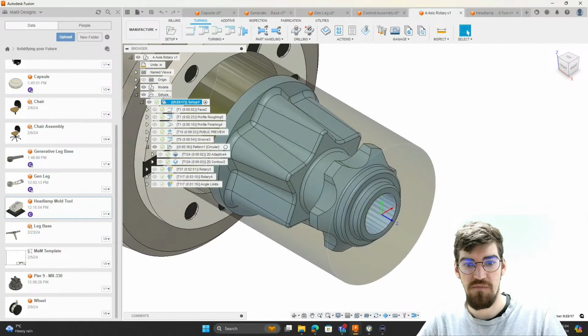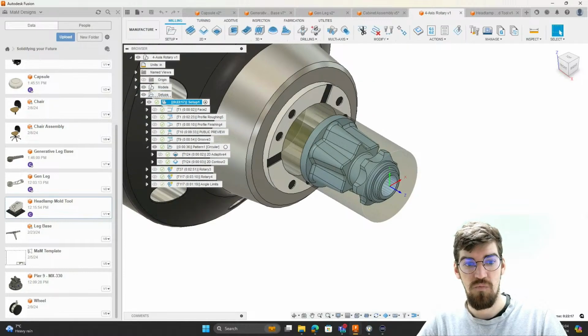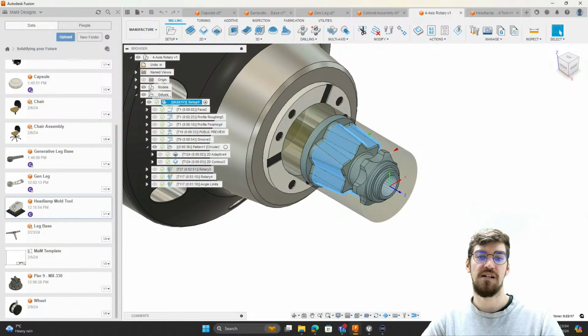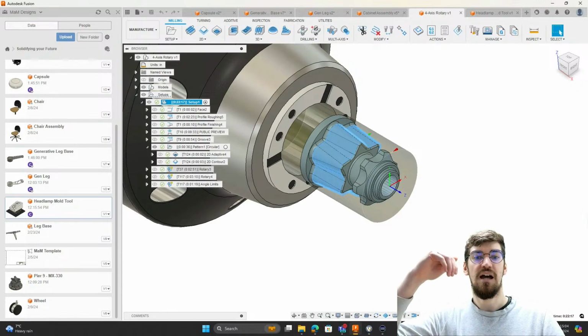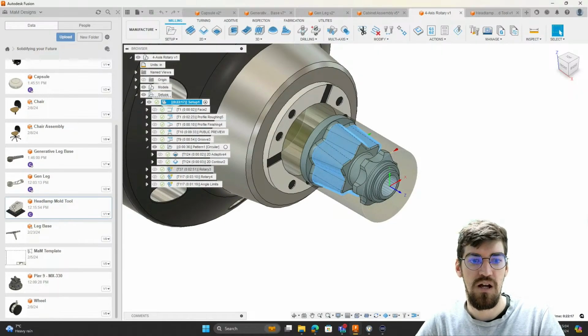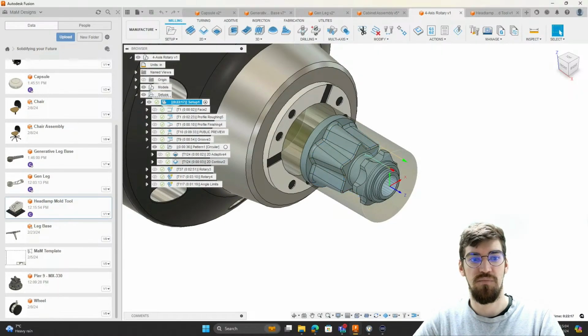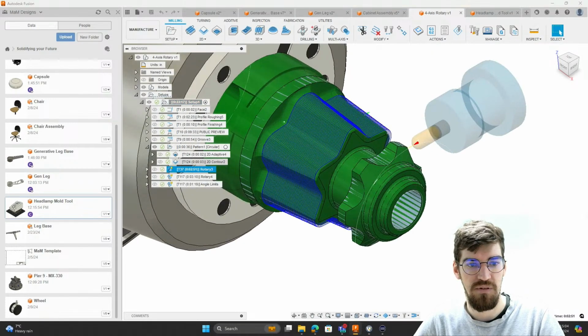Using some of the tool paths that we've got available to us within the extension, one of those is our rotary option. This is going to allow us to have simultaneous turning strategies available to us, so 4th axis, and allow us to vary the depth of the tool as it goes and rotates around your component. So we've got the ability, using our rotary option over here, to choose between